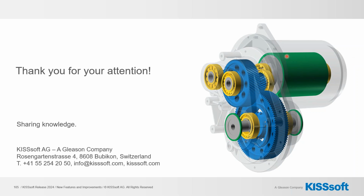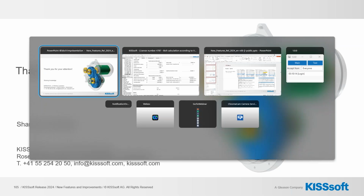Can KISS Design output the system level backlash? Or also, can it output system level torsional stiffness? Yes, it does. It gives the value in the main report, actually. In the main report, when you do a KISS design calculation,